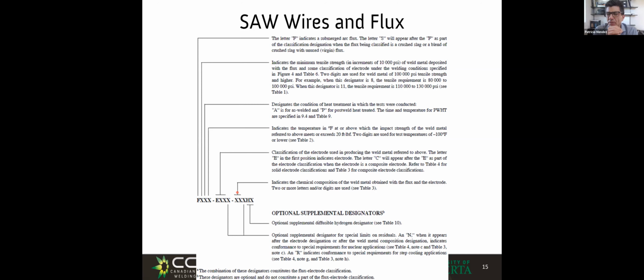And now things get interesting because, for example, if I want to weld on rusty plate, we all agree by now, we want higher silicon and higher manganese. And do we get it from the wire or from the slag, from the fluxes? We have to choose, because if we get the manganese from the wire and the manganese from the fluxes, we might end up with a diamond hard weld that is going to crack, right? And so typically wires and fluxes are sold in some sort of a package. If we want to mix and match, that's okay, but we have to know what we're doing.